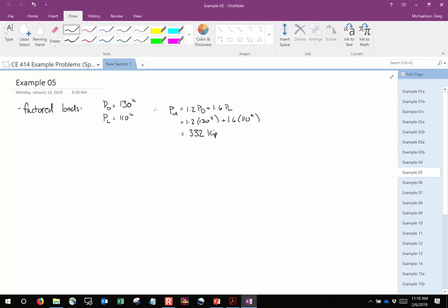That's a great question. Now, remember, live load reduction is intended to account for the probability that not the entire tributary area is being loaded. But when it's all said and done, there's still uncertainty associated with that magnitude. Hence why we apply that load factor. We're applying a 1.2 load factor for the dead and a 1.6 load factor for the live. We're still applying a higher load factor because even though we perform reduction, there's still more uncertainty associated with the live load than there is the dead load.